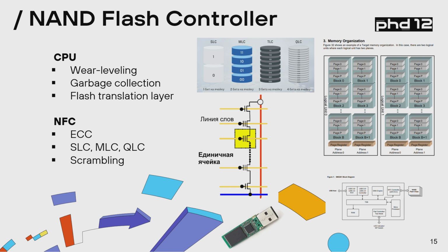Which means that if you want to reverse engineer a USB drive, you actually need to learn a lot about NAND and how it operates, because otherwise you won't know about SLC, MLC, and QLC modes. Maybe you aren't even thinking that in order to do proper reading from NAND, you need to set the right mode.